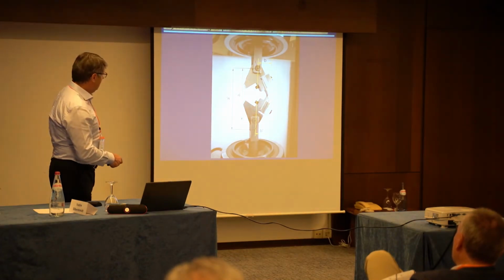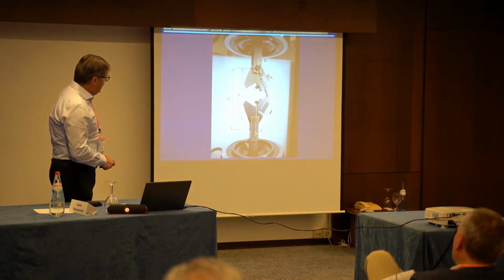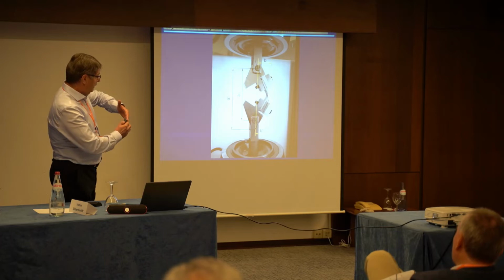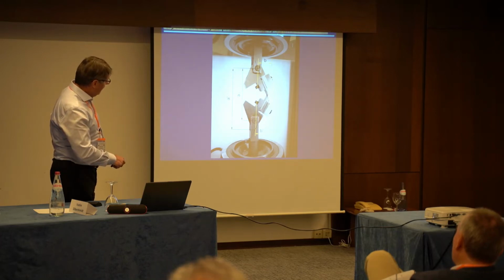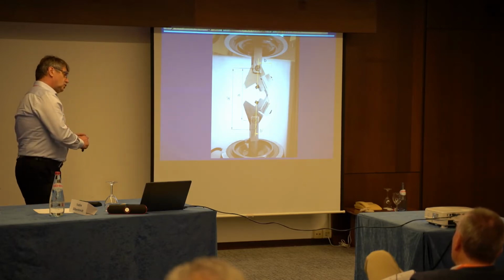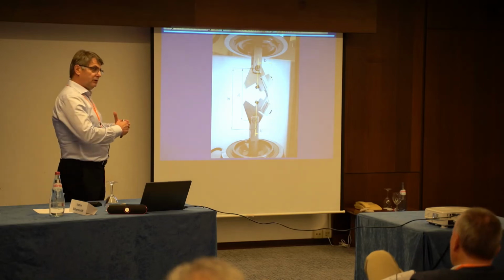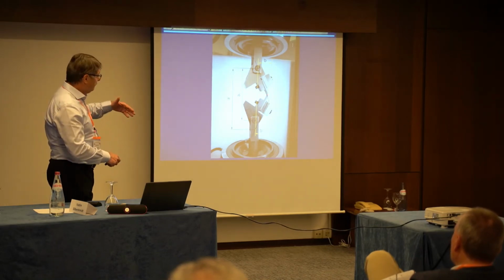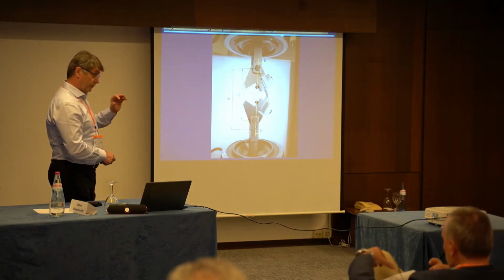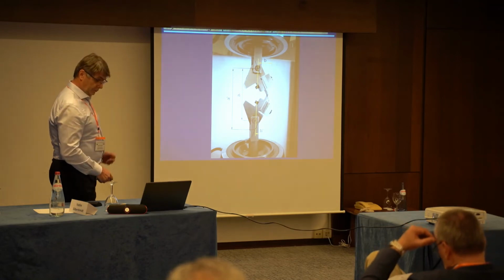Because when we start with the loading, we are here in the B position, and the initial distance between pins is A0. Then you start to rotate, and you come to position A prime, and also you change the D position to the B prime position. So now you should consider the change of moment, because moment has the most influence on the stress which you have on the tip. And of course we are looking just at the exact middle point, where the highest equivalent stress is, as we proved numerically.